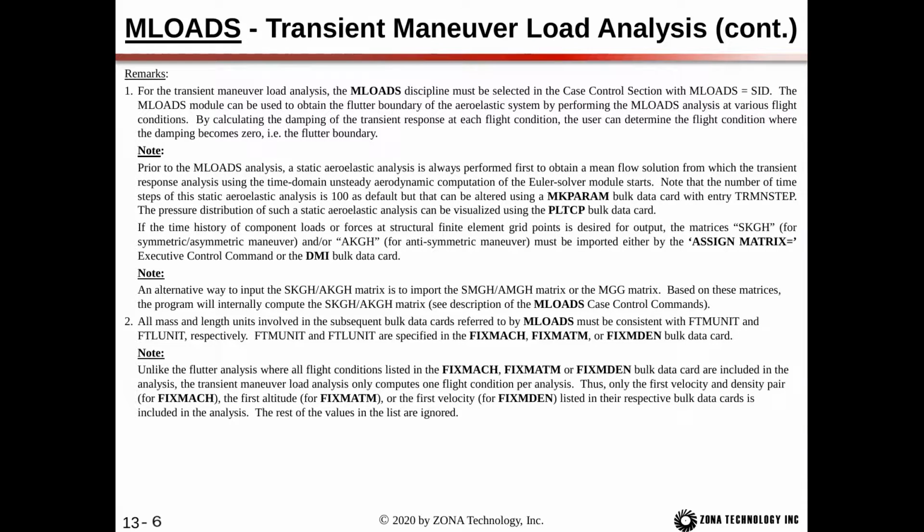Now, prior to the MLODS analysis, a static aeroelastic analysis is always performed first to obtain the mean flow solution from which the transient response analysis, using the time domain unsteady aerodynamic computation of the Euler-Solver module, starts. And note that the number of time steps of the static aeroelastic analysis is 100 by default, but you can alter this in the MKPARAM card with the entry TRMNSTEP. And the pressure distribution of the static aeroelastic analysis can be visualized using the PLOTCP card.